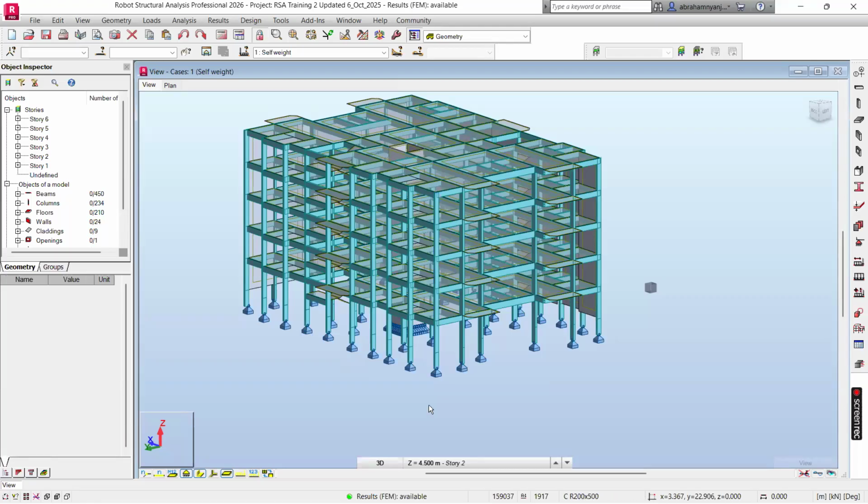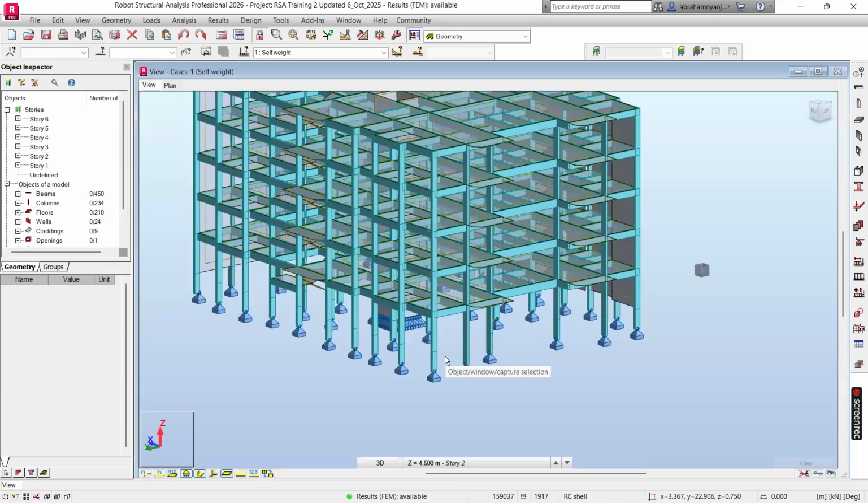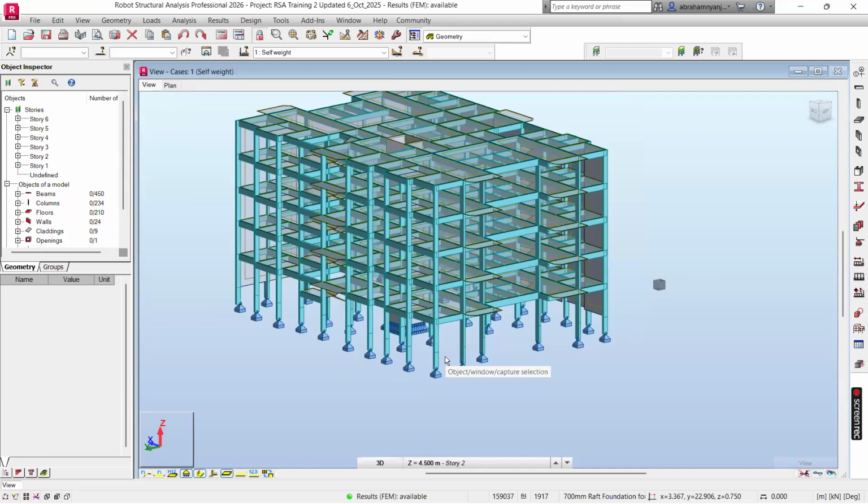Foundations are divided into very many types: deep foundations and shallow foundations. Deep ones would be the piles, and as you're aware, they can be end-bearing piles or friction piles, depending on the load transfer mechanism. End-bearing piles transfer the load to a firm strata.